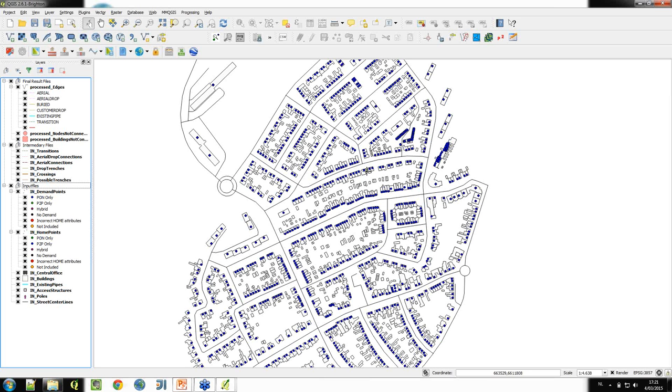Thank you, Raf. So let me show you how we make an initial design with the FiberPlanIT Designer. I have QGIS open here, which is an open source GIS tool, and I will use this tool to visualize all the GIS data and the output of the FiberPlanIT Designer. For the demonstration, I have chosen an area where I have building information and address point information, and I have also loaded the street center lines for my area.